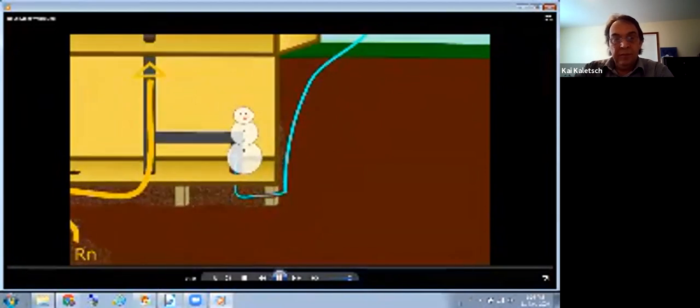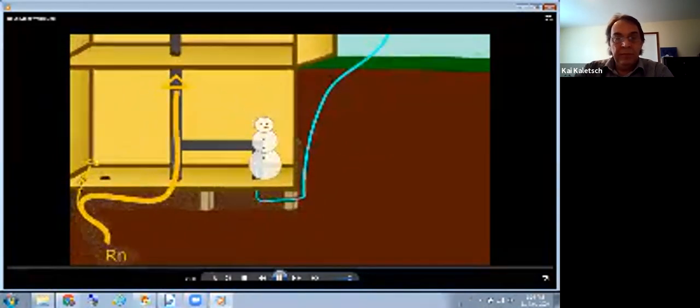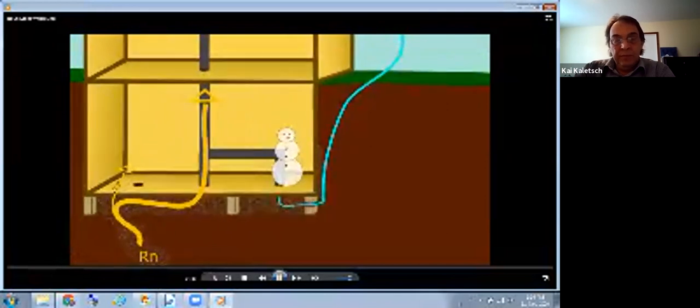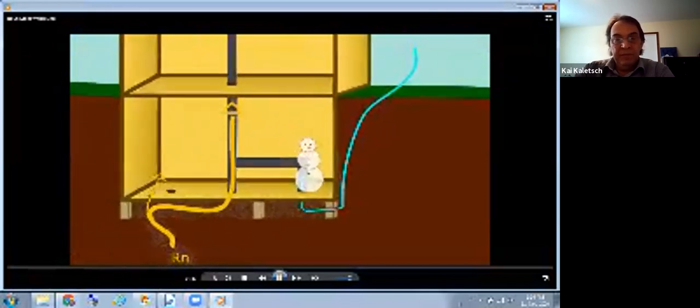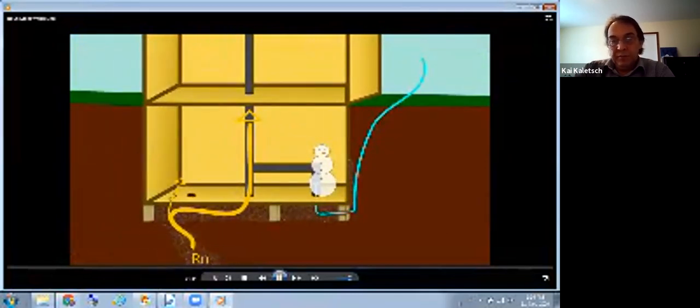It also lowers the suction on the other side by pulling in outdoor air, plus now you have a large unsightly jumper. Even worse, the problem might not have even gotten solved. In theory, the mitigator depressurized the entire slab and reversed the airflow through the cracks, but this isn't necessarily the case. The actual pressure at the crack was never measured. There might not even be access to the crack if it is at the expansion joint under a finished wall.